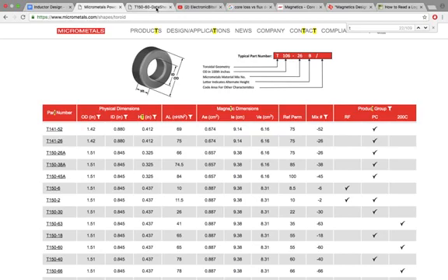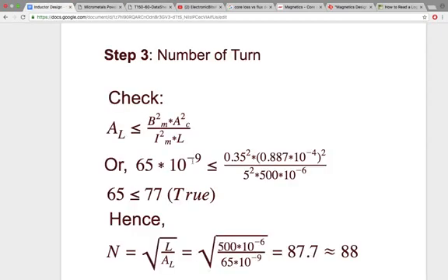Yeah, so basically this cross check is also helping in one case. If your area is this, now you can see it is being justified here. Now the AL condition is being justified here. So using this, if it is justifying, you can choose the suitable core with suitable AL value also.